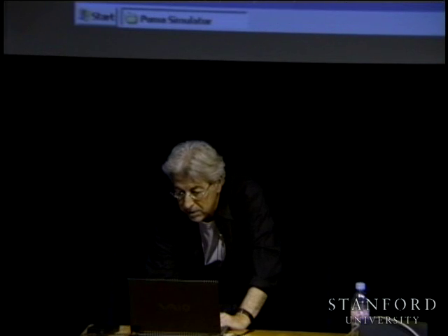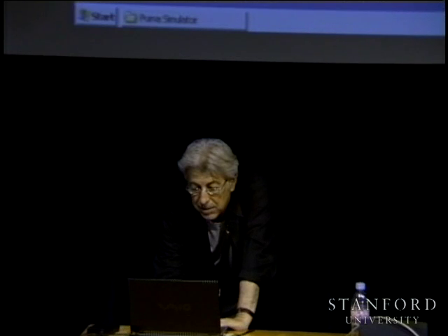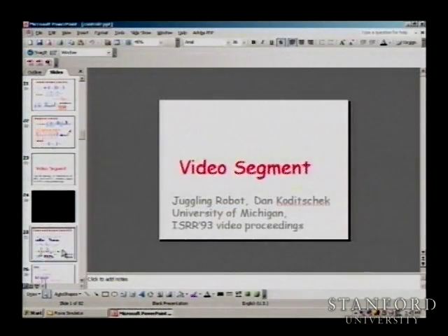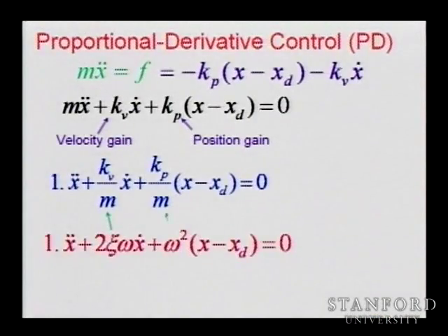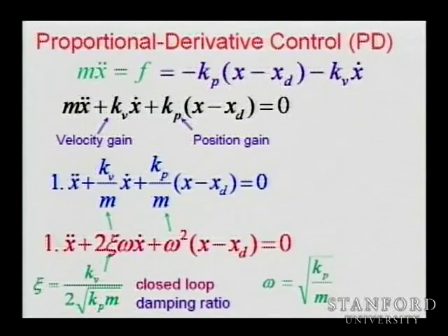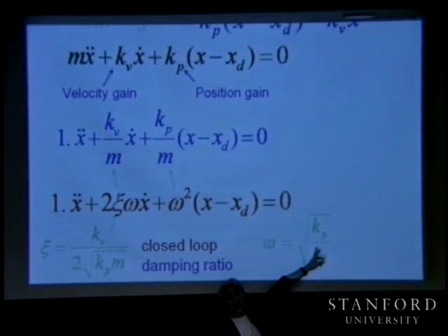So this Kp that we have here cannot go too high. We want it as high as possible to increase what? What does it do when Kp is high? Disturbance rejection, because errors and dynamic coupling coming from other links will be rejected. It's stiffer.